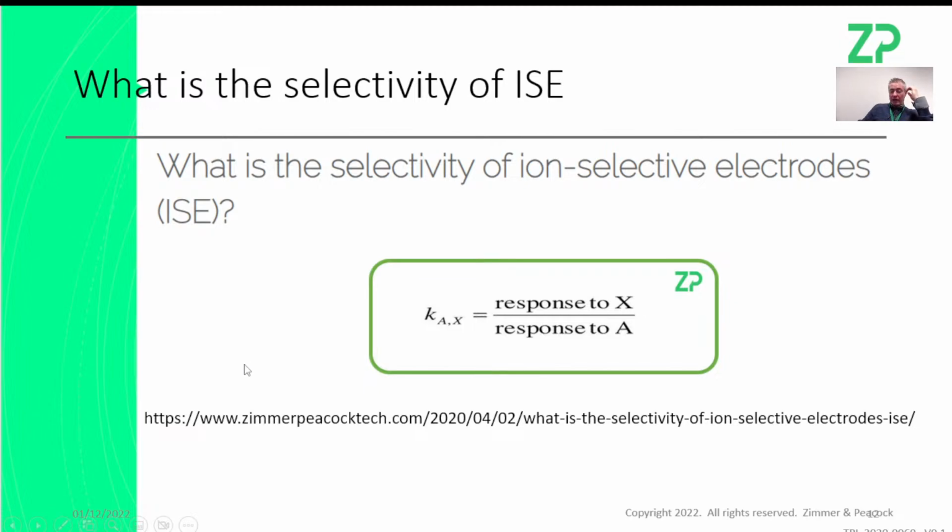I've got all sorts of theories why. Impedance spectroscopy is very feature rich. You can get both the capacitance of the electrode and the resistance of the electrode. So I'm really tempted to say you might even be able to improve it with impedance spectroscopy. But in answer to your question, I think the unselective electrodes are pretty good.